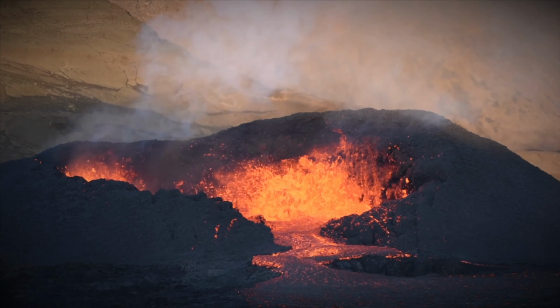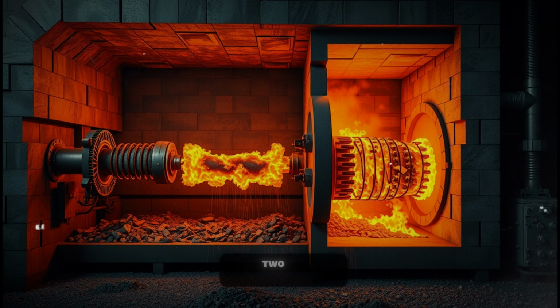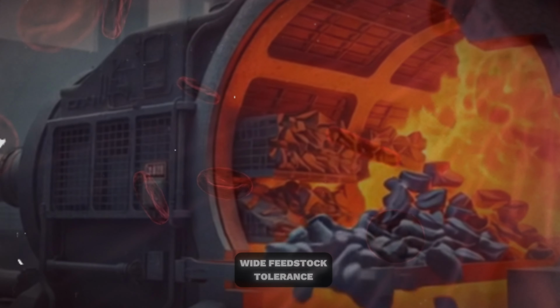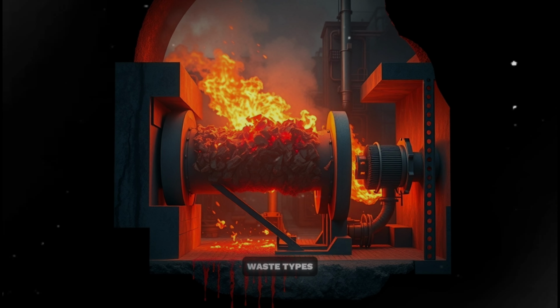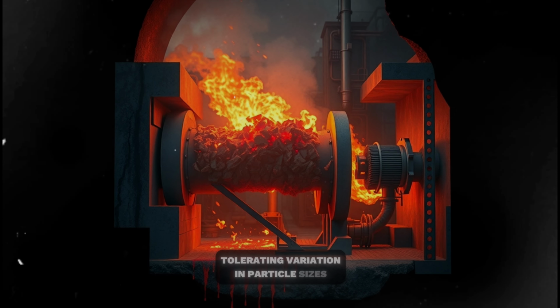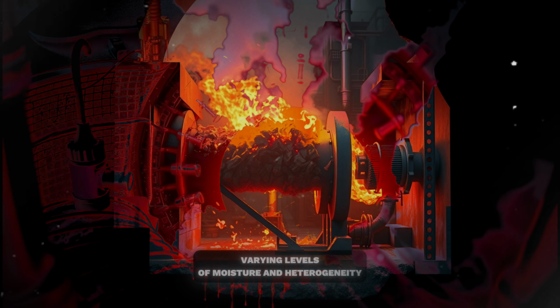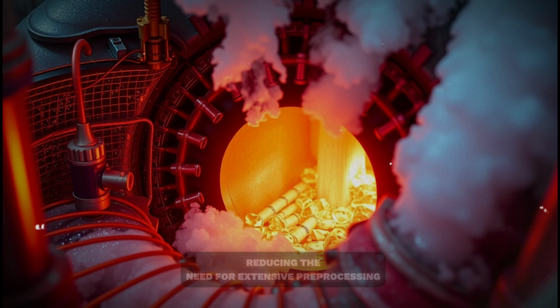This grinding action is critical because it exposes more surface area to the heat, helps to avoid char buildup on the surface of the particles, and results in a more uniform and rapid pyrolysis process. 2. Key technical advantages. Wide feedstock tolerance. This system can accept a wider range of biomass and waste types, tolerating variation in particle sizes, from microscale up to a few centimeters, and varying levels of moisture and heterogeneity, reducing the need for extensive pre-processing.